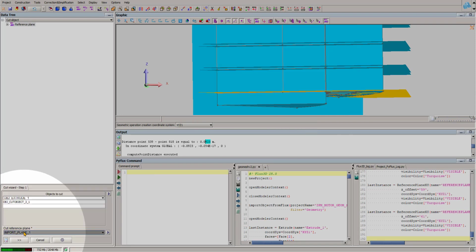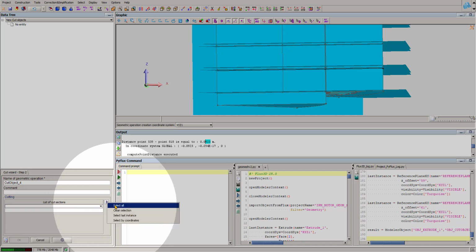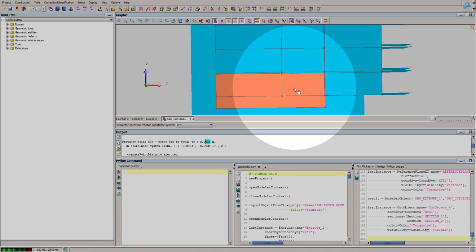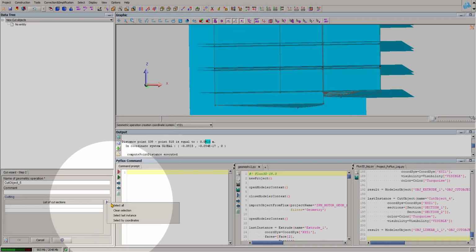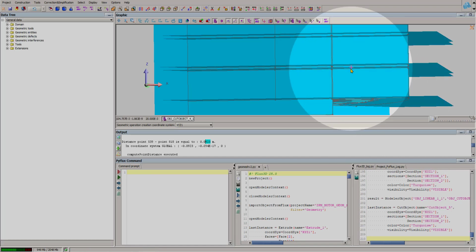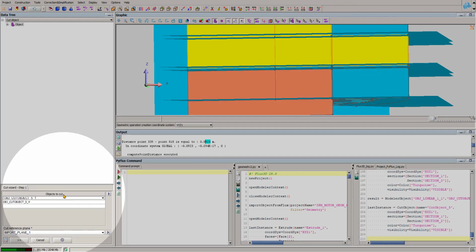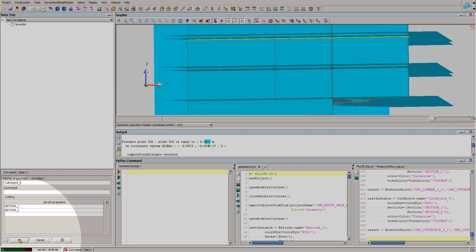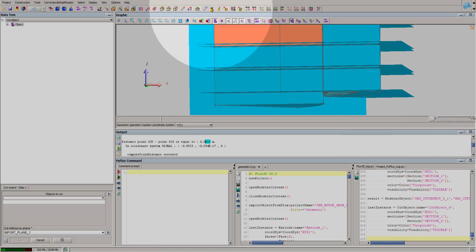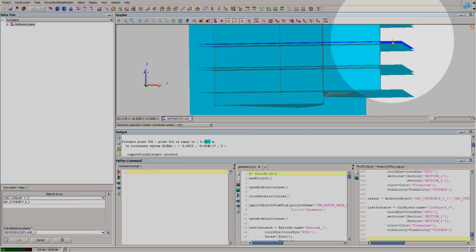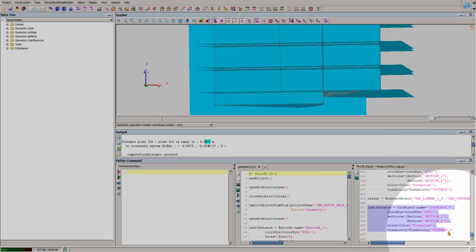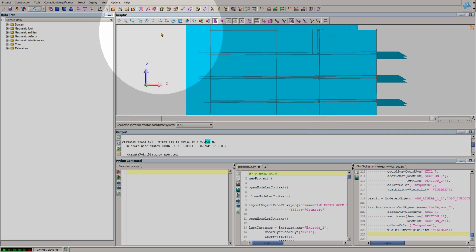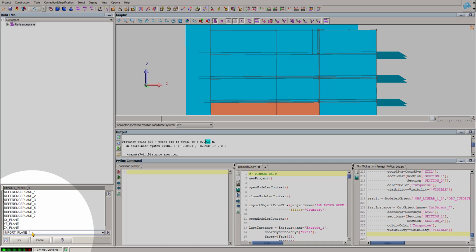So later on I will have intermediate layers I will mesh with extrusive mesh, and then in the junction layer it will be a tetra mesh, and like this I can optimize as I want the mesh, and I will not have any issue to make a mapping between the extrusive mesh and the tetra mesh. So once I created the reference plane, I can cut accordingly each layer, and then you will see afterward I will have several layers, a junction layer between the step skew layers that I will mesh in tetra, and then the intermediate layer will be meshed in extrusive mesh.